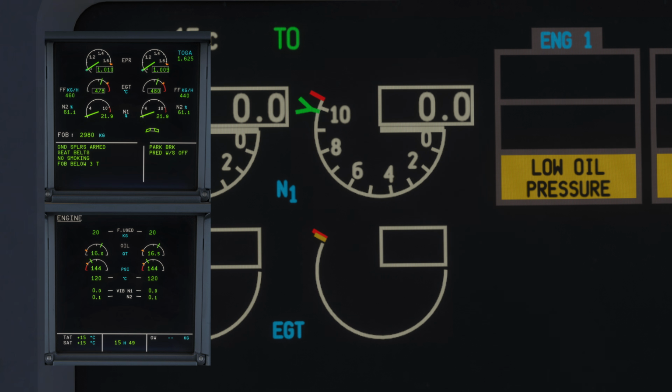If there is a higher pressure at the outlet of the engine, then it is producing forward thrust. On the other hand, if there is a higher pressure at the inlet of the engine, then the engine is actually producing drag. Therefore, an EPR of 1.0 is going to be neutral thrust, while an EPR, for example, of 1.2 means that you are producing positive thrust.